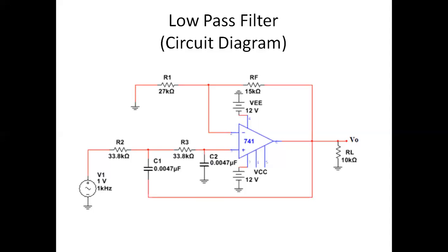This is the working principle of the filter: at low frequency it selects the signal and amplifies it according to the amplifier gain set as 1.586, and we get the output. As the frequency increases, it rejects the signal, the signal gets attenuated and grounded through the capacitor rather than getting selected by the op-amp.